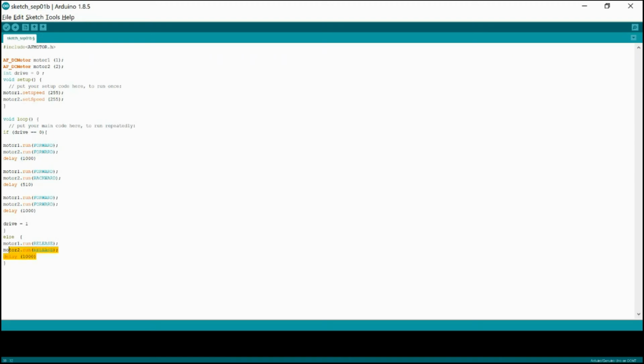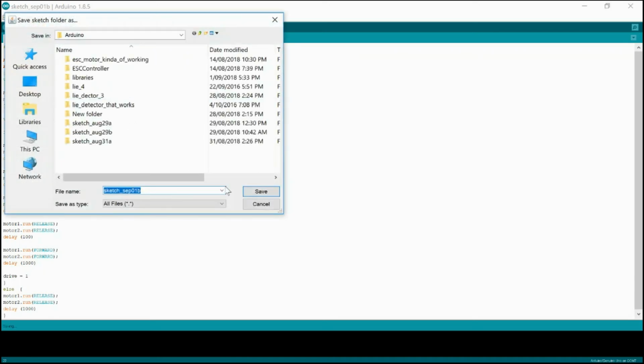What I also like to do is I like to put a bit of a break in here in between all the motors doing what they're doing, and we'll just make it 100. Just that way it gets that sort of 1/10 of a second break before it then puts all the power straight back to the motors. So if you're going forward, backwards, it's a lot of power just hitting the motors, and we don't want to burn the motors out. So if we test this, alright.